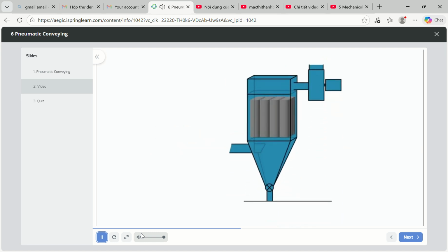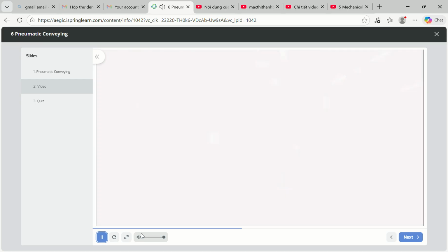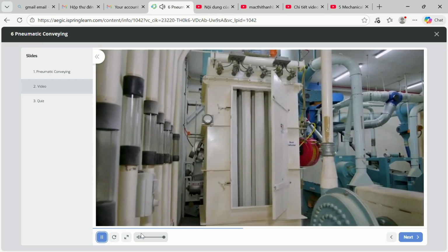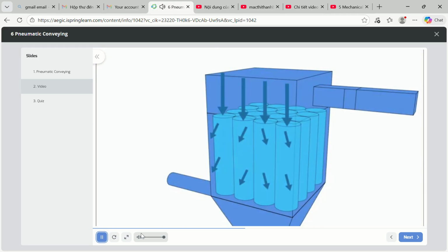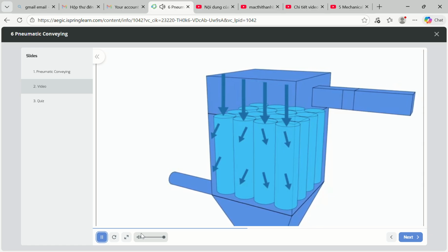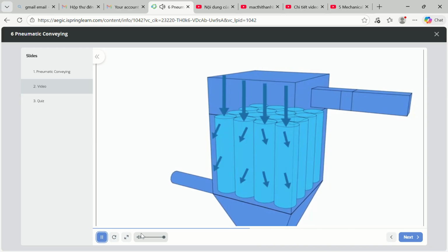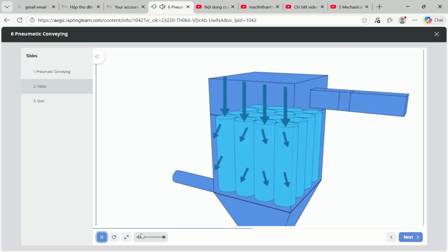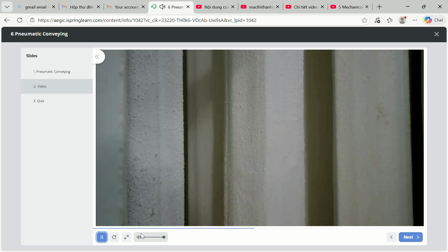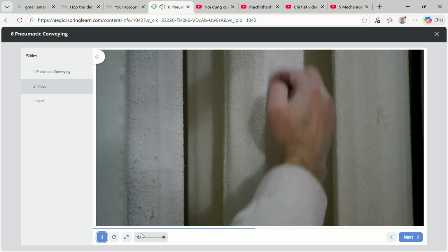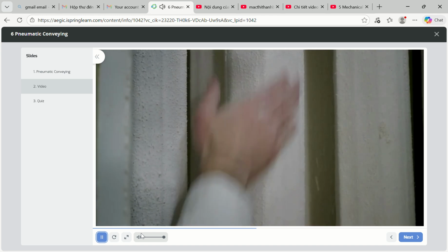Other types of filters rely much more on fabric filter sleeves to separate the solids. The filters are usually cleaned by a system that intermittently blasts compressed air into each filter. The blast may only last a fraction of a second and only clean one row of filters at a time. Despite the automatic cleaning, the filter still needs to be cleaned or replaced periodically to allow air to keep flowing.